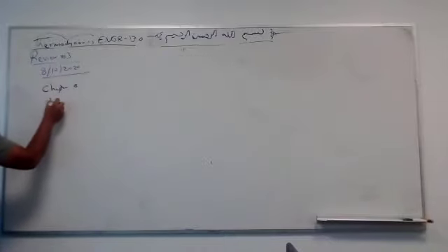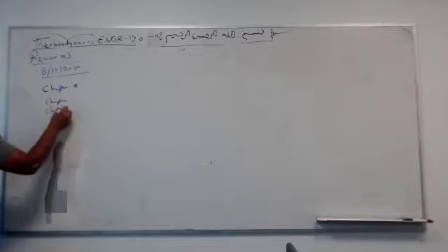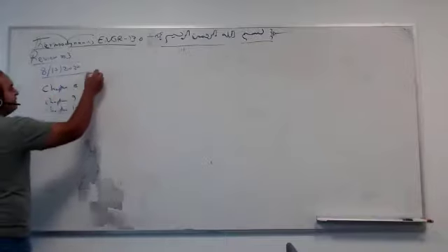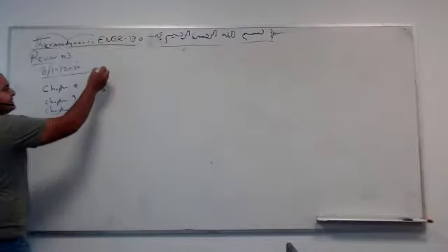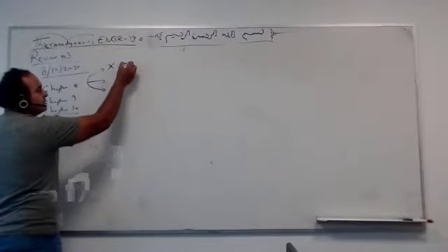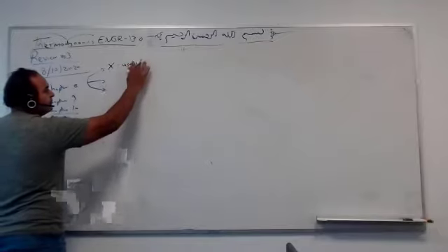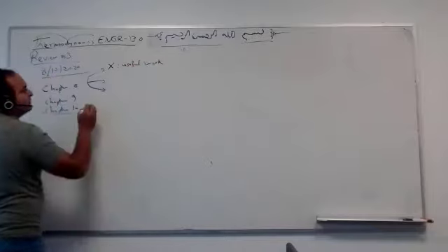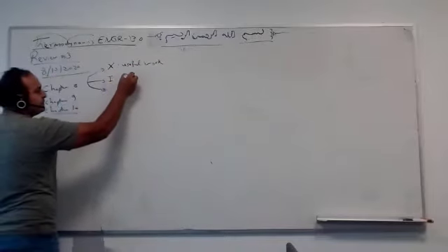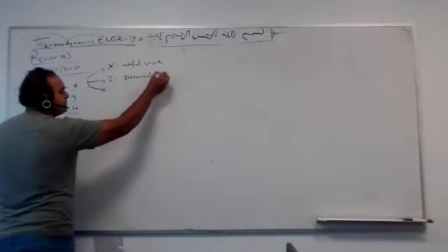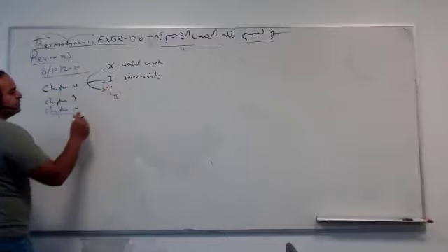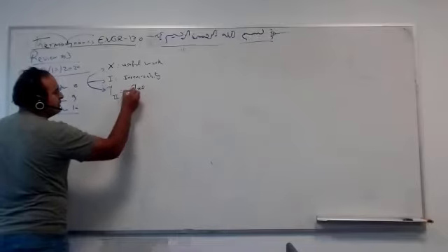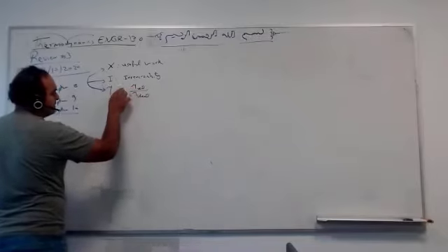We have chapter 8, chapter 9, and chapter 10. Three chapters. Let's start with chapter 8, where we have three definitions. Only three definitions. The first one is exergy, which is useful work or work per unit mass. We have irreversibility, which is useful minus non-useful. And we have second law efficiency, which is eta real over eta ideal, always less than 1, or it's 1 if the system is ideal.